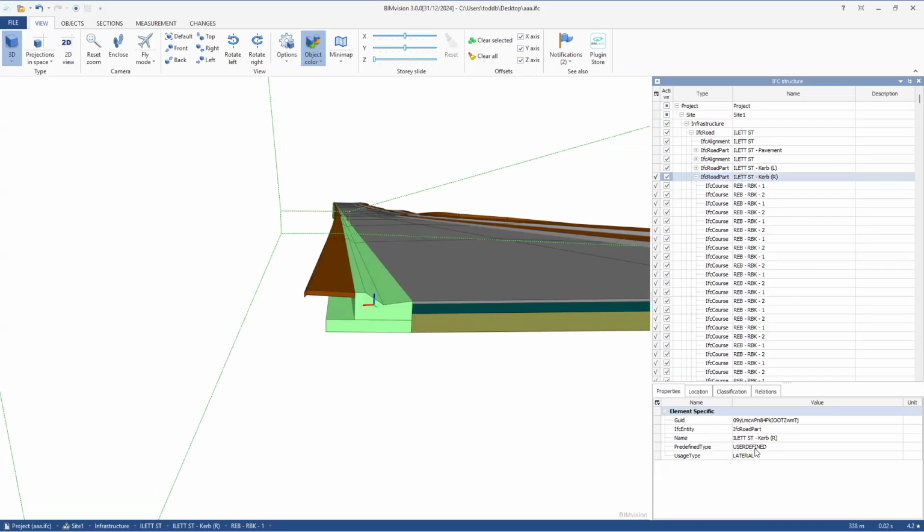But underneath, you get to see information about it. So you can actually see details on it, classification. Well, there's none set, but you can see what it is. And if you've got a fancy version of the IFC viewer type stuff, you can actually do quantity takeoff for this sort of stuff because these are all volume based solids that have been extruded. So it's like the B-rep mold that we used to make out in the model viewer.